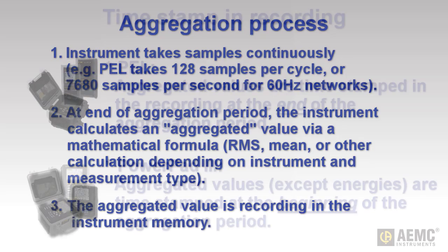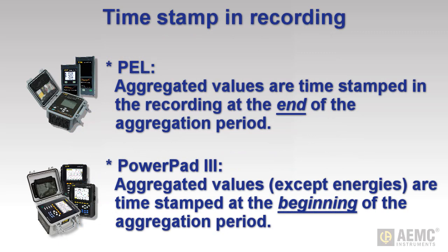The time at which the aggregated measurement is recorded in memory depends on the instrument model. On PowerPad instruments, the timestamp of the aggregated measurement for most parameters is at the beginning of the aggregation period, while on PEL instruments, the timestamp is at the end of the period.